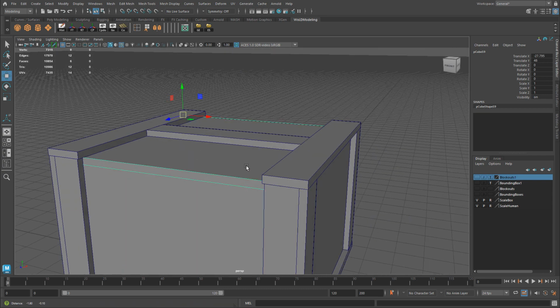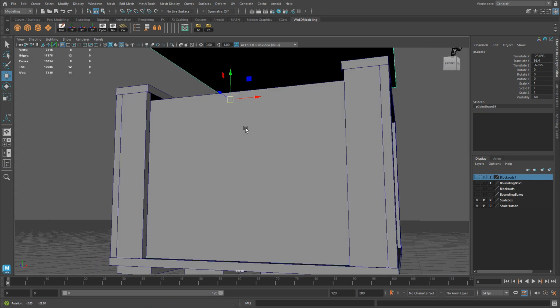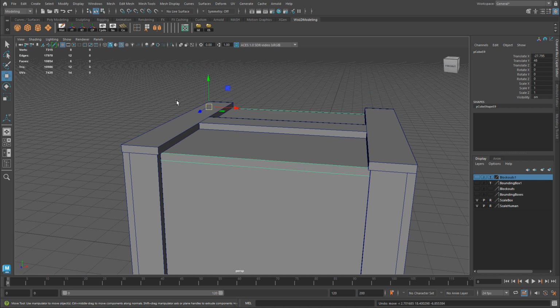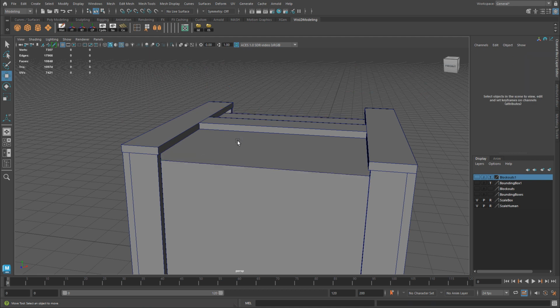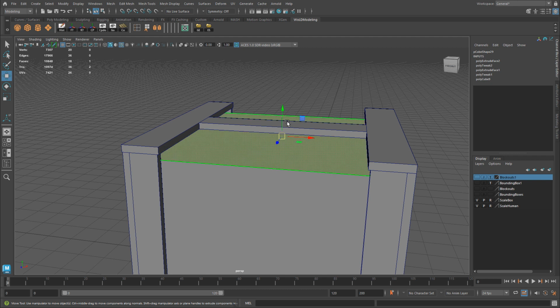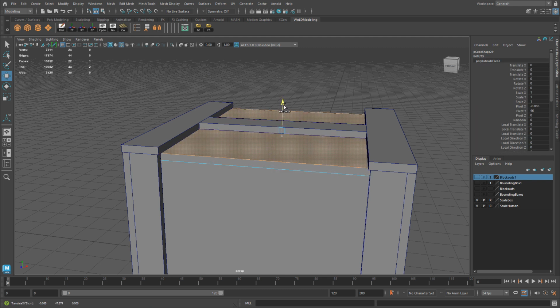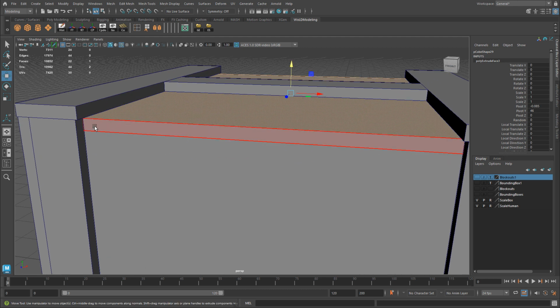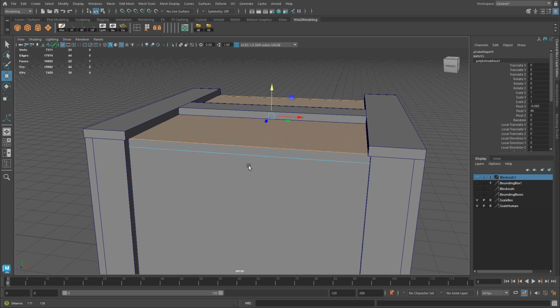And then for the top one, again, I have two faces that are being hidden, so I would either have to delete them, but why have this as a separate piece of geometry where I can just take this top face and then extrude it? And the reason I'm extruding this is because I introduce an extra face that I can detach in the UVs and have it separate, so maybe I can apply a different texture to it, and it will look like it's being separated. So it might be a little bit darker plywood, and then this might be a lighter plywood. So it gives me a little bit of flexibility to add a different texture for this face only.